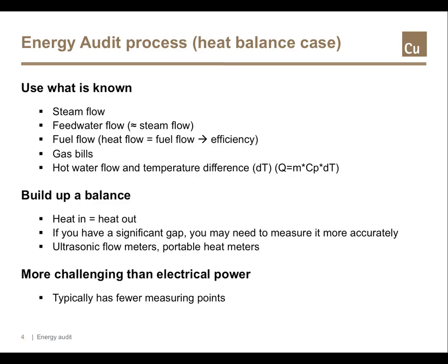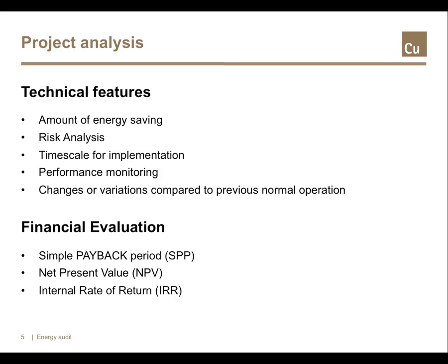An energy audit is always concluded with a report presentation and a submission to the energy manager. The energy report should include technical features and financial evaluation. Technical features include the amount of energy saving, the risk analysis, timescale for implementation, performance monitoring, changes or variations compared to previous normal operation. In the financial evaluation for a typical energy review, the calculation of a single payback period should be sufficient information, though net present value or internal rate of return are also used.